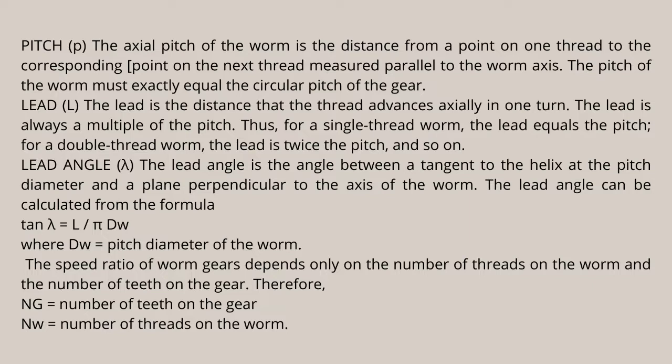Lead. The lead is the distance that the thread advances axially in one turn. The lead is always a multiple of the pitch. Thus, for a single thread worm, the lead equals the pitch. For a double thread worm, the lead is twice the pitch, and so on. Lead angle.